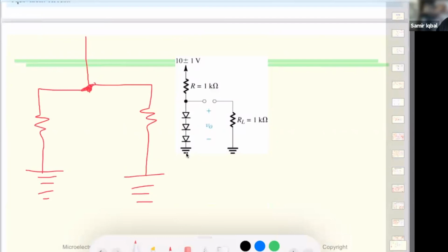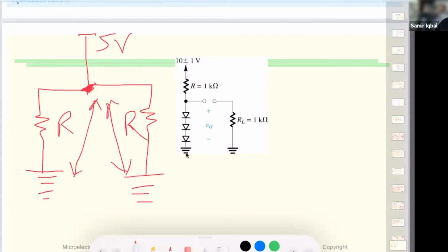All right. Everybody agrees. Who said that? I did. Okay, give me your name. Oh, Nestor. Okay, what Nestor just said. Say at this point I have 5 volts, and this is R equals R. Both resistances are the same. So from here to here, and from here to here, what can you tell me about the voltage across these two resistances? They're going to be the same.